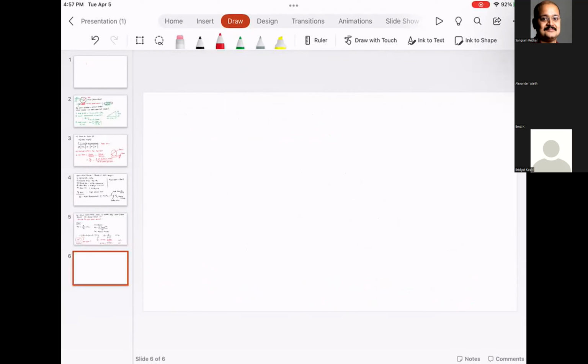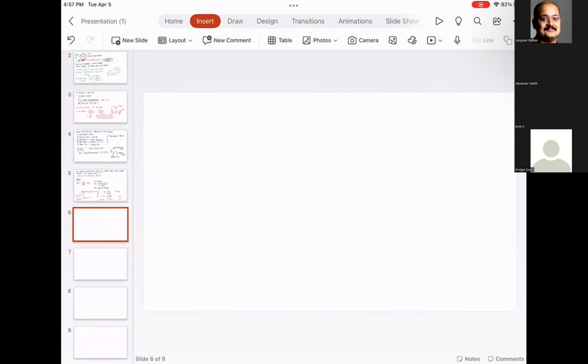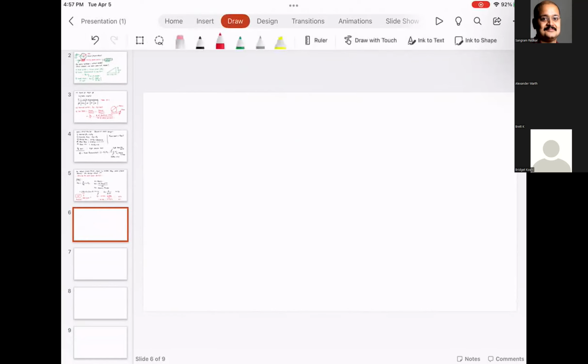Then we have to find out something called the dynamic load. Now, believe it or not, finding dynamic load in the case of wormwheel is extremely simple. How do you find out dynamic load in the case of wormwheel? So step 2, WD, the dynamic load, is equal to WT divided by CV.